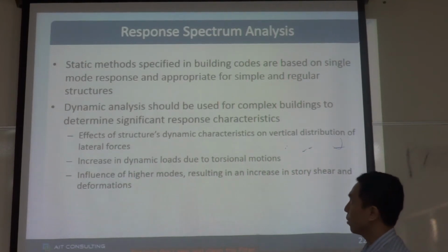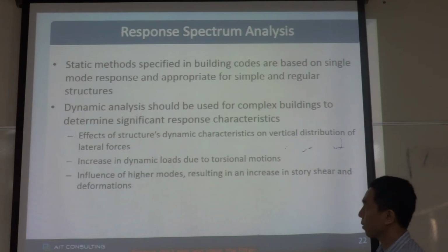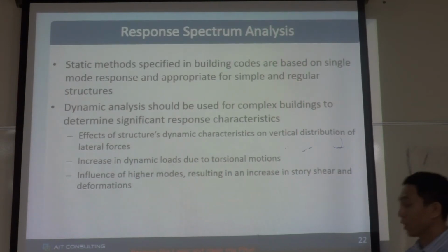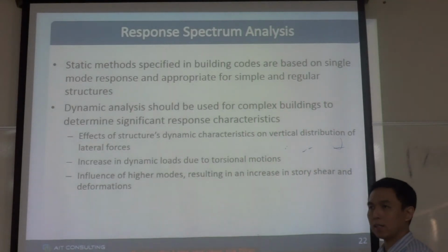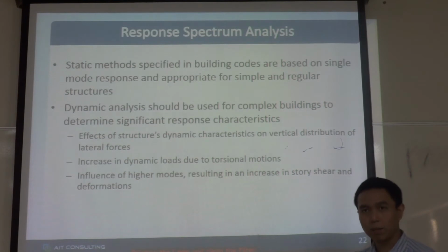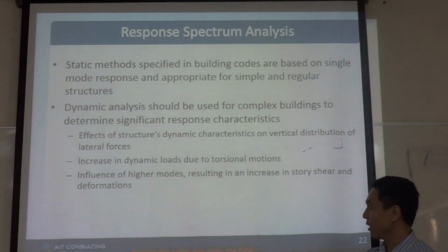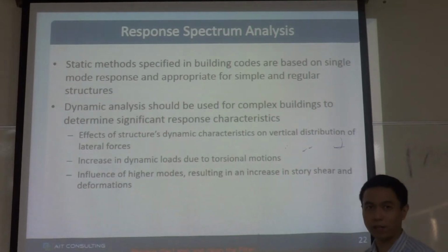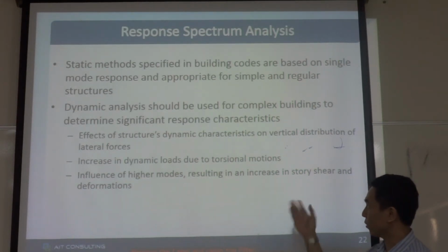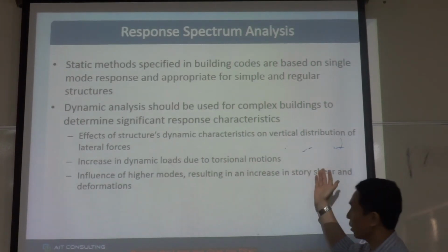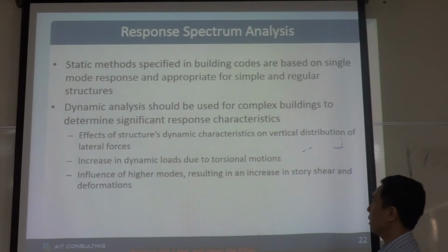The difference between static analysis and response spectrum analysis is the distribution of the forces. When you do the static analysis and dynamic analysis, the design base shear is the same, but the distribution of the forces in the model is different. Response spectrum analysis considers the dynamic characteristics and distributes the forces according to those characteristics.